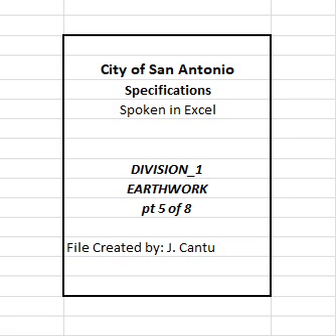Construct the final layer with graded material so that the density and uniformity is in accordance with section 107(3)d, compaction methods. Break up exposed oversized material as approved. When ordinary compaction is specified, roll and sprinkle each embankment layer in accordance with section 107(3)d. 1. Ordinary compaction.